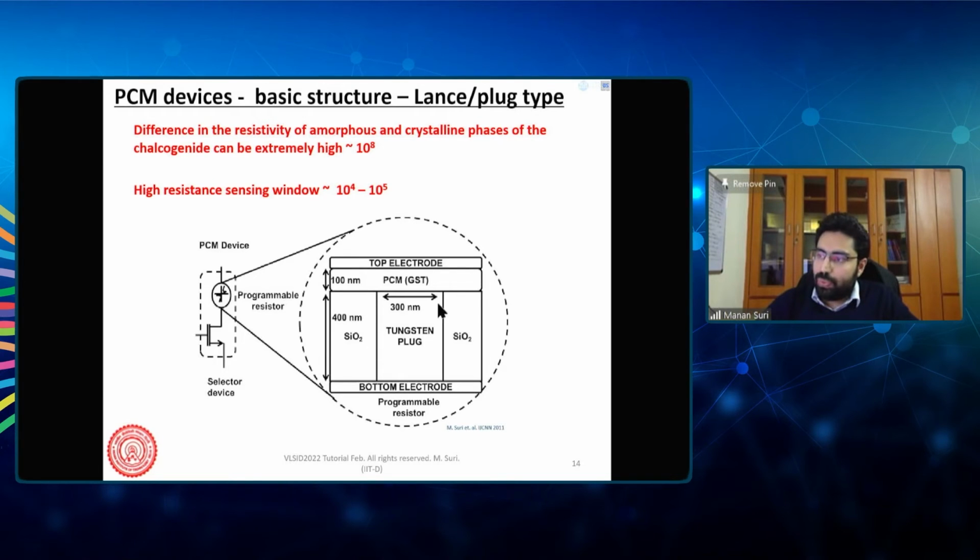Not only electronic engineering, you also do some thermal engineering, because you want to maximize your heat dissipation in the chalcogenide interface for efficient programming. So while building this structure, you would choose materials which don't allow heat to escape in unwanted directions, and heat concentrates at a specific spot to have low energy based programming.